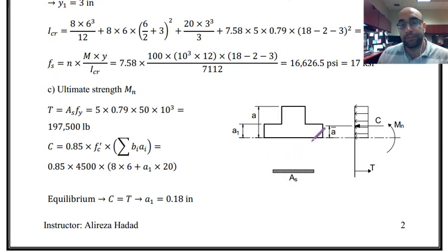As you can see, this is the neutral axis. As we increase the amount of load, the cracks will be larger and wider. That's why the neutral axis is moving up as we increase the load. This is the stress block in the compression region, and the total A that I'm showing you is the depth of compression block, and then T is the tensile force that we have in steel, and that is AS multiplied by Fy.